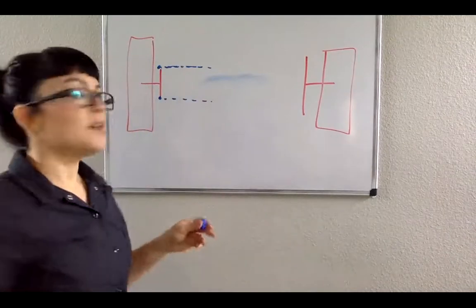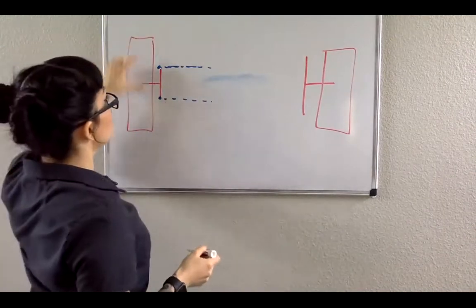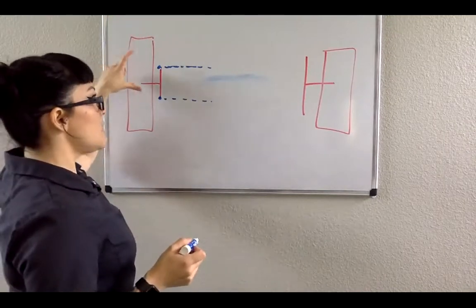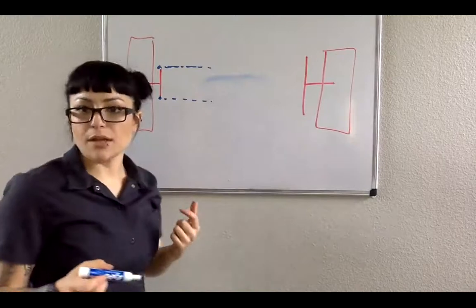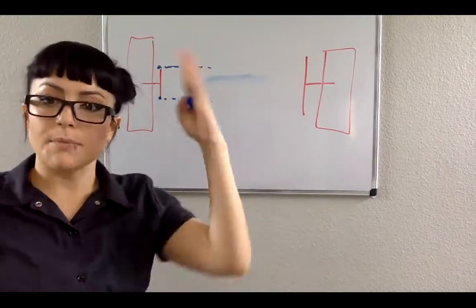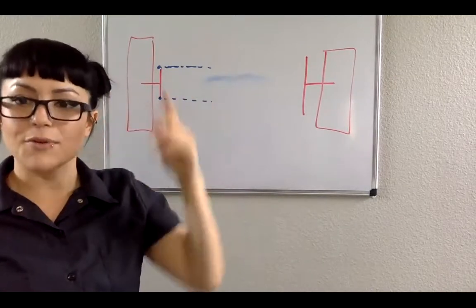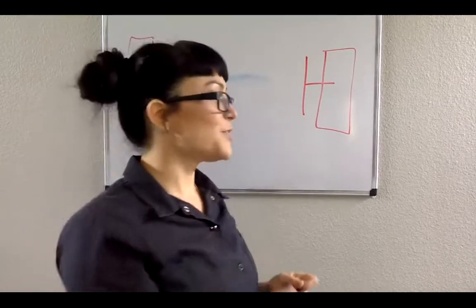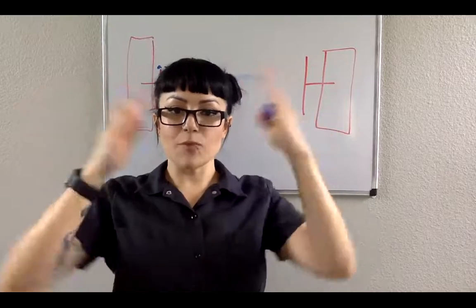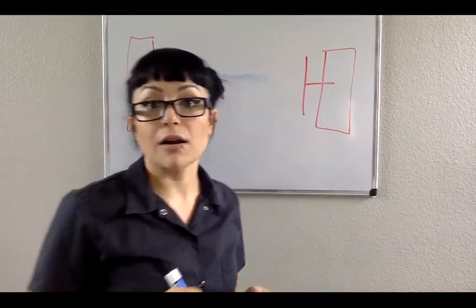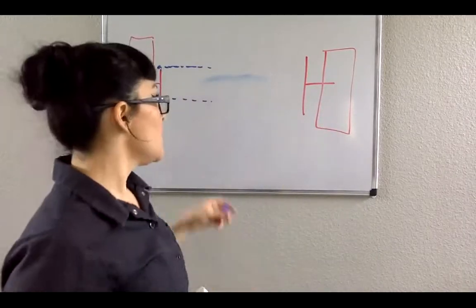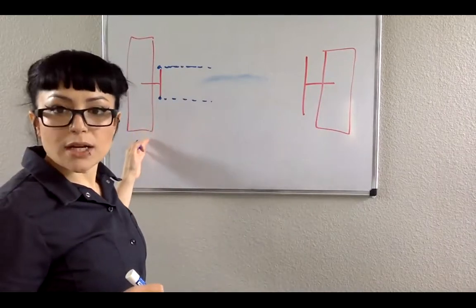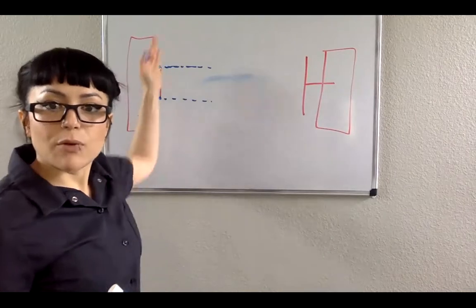The problem with this is as my tire moves up and down, it stays in the same position. We don't get a change in alignment, meaning camber. You guys know camber, right? Where the tires move in and out. Not yet, because you have probably not watched the steering lecture. But camber is going to be that inward or outward tilt of our tire and wheel assemblies. You'd think, well, that's perfect, right? We don't want any alignment changes as my wheel goes through the arc.